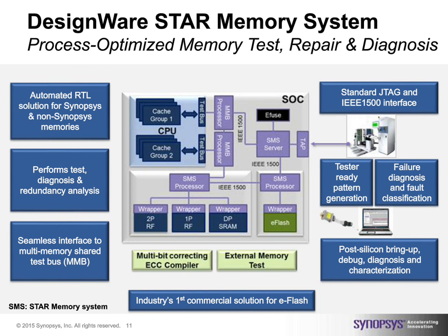Now those processors have to be intelligent enough to handle the technology on chip, to handle the defects in terms of detecting them, diagnosing them and repairing them. So all of that intelligence is needed in these purple processor boxes. Now, of course, with the STAR Memory System, for some time we have provided the automation needed to generate, to insert, and verify for designers, and for post-silicon purposes to do the pattern generation, the analysis of results, the classification of faults, finding out exact locations, and so on.